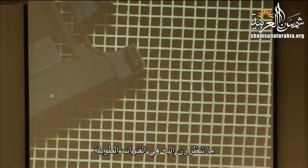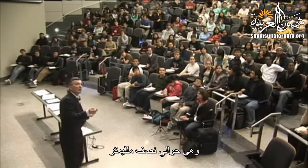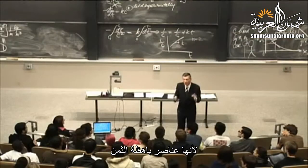This is a piece of ceramic because platinum and rhodium and all of these other elements are so expensive. See, this thing's having a hard time, so we'll cheat a little bit. We'll put this here, and then it'll focus. All right. So what you're looking at, these are long channels, and just to give you a scale, this is about 1/2 of a millimeter. So these are about 1/2 millimeter square, and they go all the way down for a length of about 8 inches. And then the walls, the interior walls, are coated with a very, very thin layer of platinum, palladium, and rhodium, because these are expensive metals.